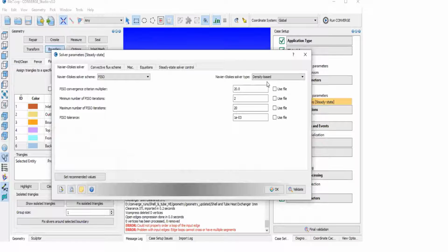I'll give you a short reason. Here there is nothing like supersonic or subsonic flows, but if your flow is going supersonic, then you have to use density based solvers, because at the supersonic stage your temperature starts changing, so you also have to solve the energy equation as well, right?